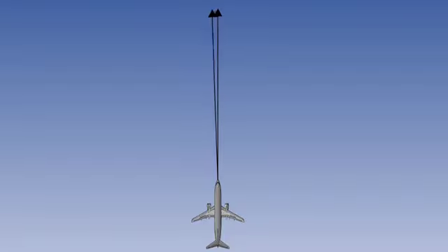Finally, there is azimuth gyro drift. In addition to any initial misalignment error, the azimuth or heading gyro may also drift. This drift rate would typically be of the order of only 1/100th of a degree per hour. But as with the topple, it is finite and would have an effect on the output.